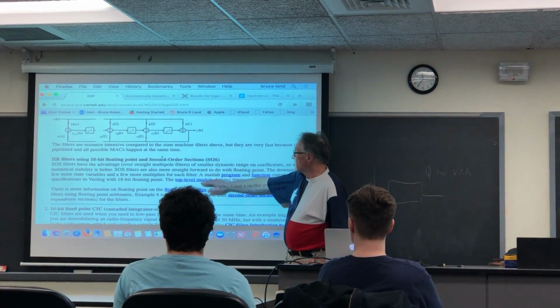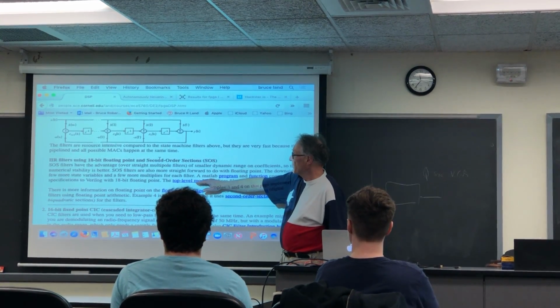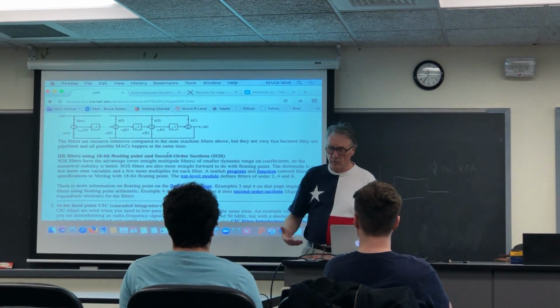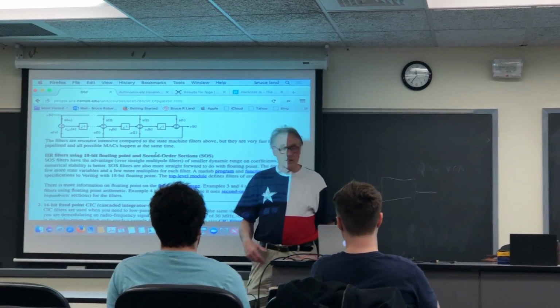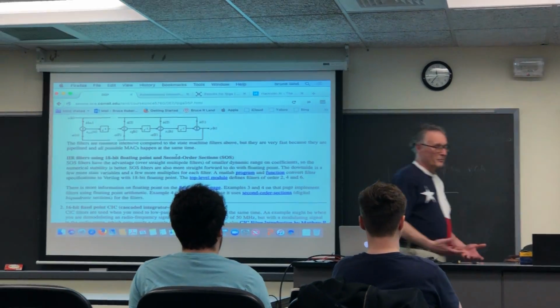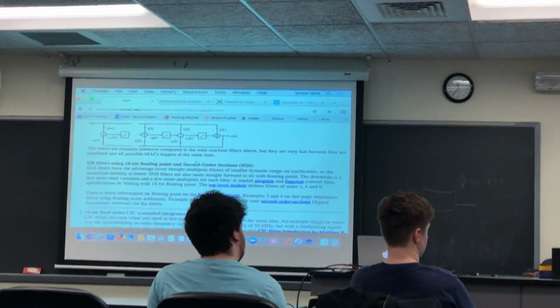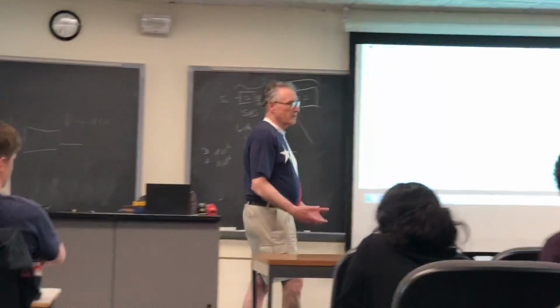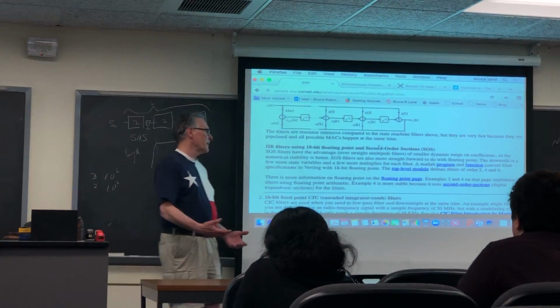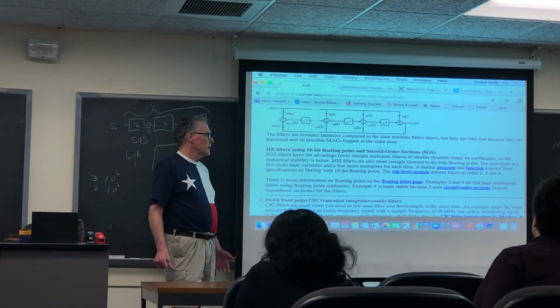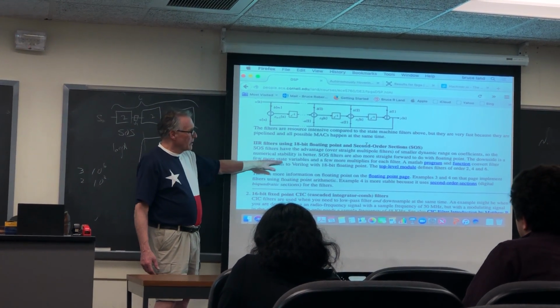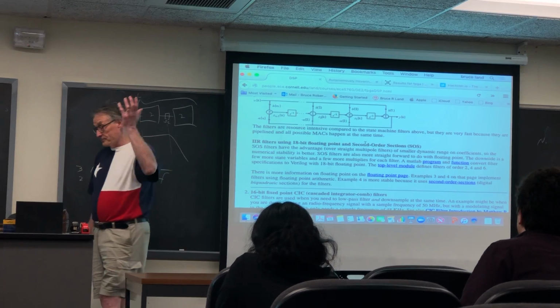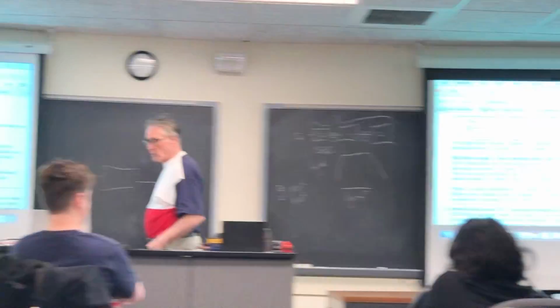So this code, the Verilog here, uses a custom floating point. In this case, that was 18-bit, not 27-bit. But since it's all in terms of FP multiply and FP add, you can just substitute the 27-bit floating add and multiply in there, and have an executing infinite impulse response floating point filter.